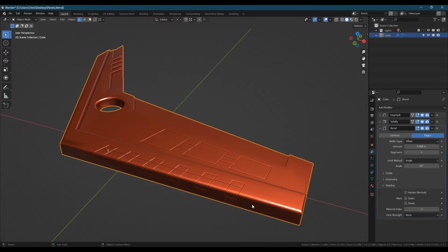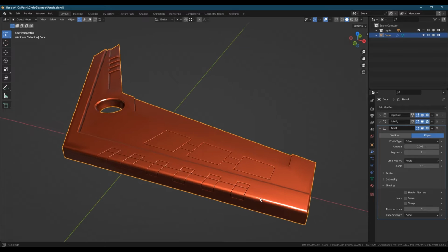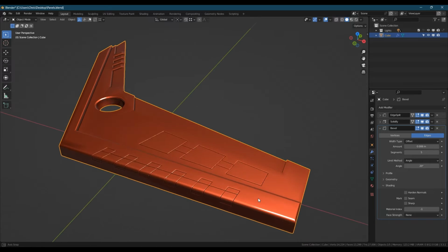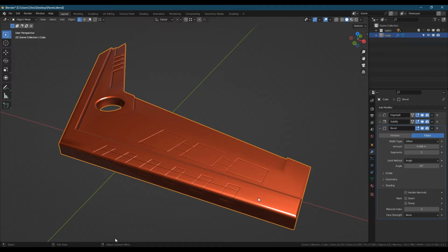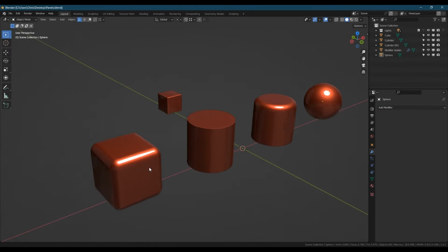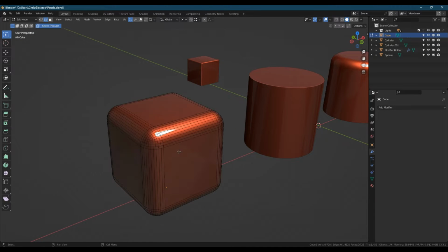So we can use edge loops, the knife tool, knife project, loop tools, the shrink wrap modifier. You can also use booleans, but the cleanup required for this technique is not worth it. Booleans are best used for establishing the form. We'll start with simple examples and get more complex as we go.